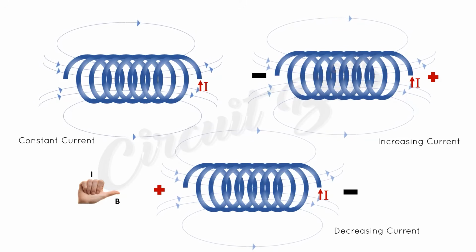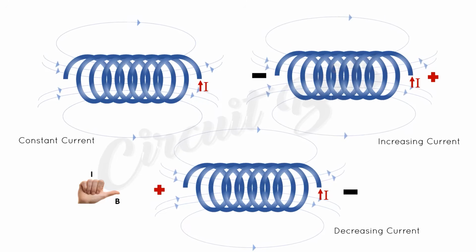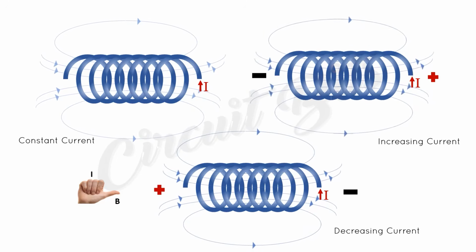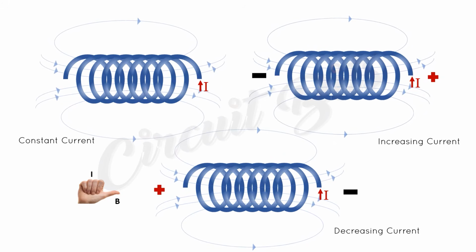The right hand rule can also be used to determine the direction of the flux, but this time if the thumb points to the direction of the flux, then the other four fingers point in the direction of the current. Inductors can have their coils wound around a material, and this material is called a core. Its essence is to increase the magnetic field and thus the inductance.